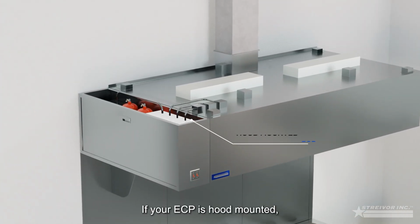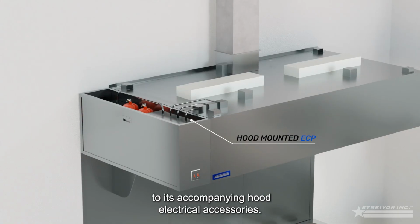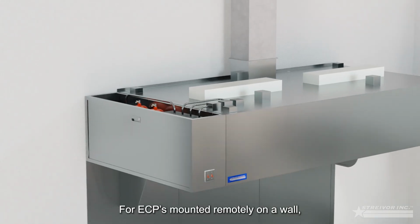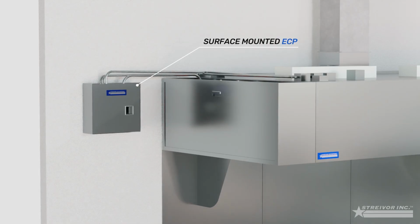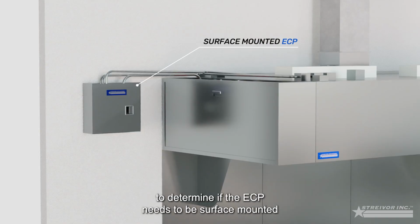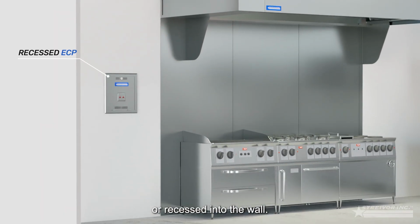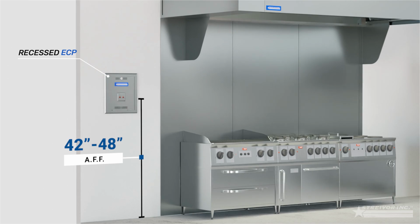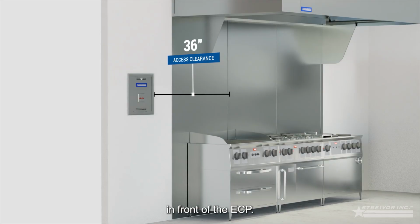If your ECP is hood-mounted, it will be pre-wired at the factory to its accompanying hood electrical accessories. For ECPs mounted remotely on a wall, the electrical wiring should be connected to its accompanying hood. Follow the ECP detail from the DemandAire drawing to determine if the ECP needs to be surface-mounted or recessed into the wall, along with the proposed height that it should be installed at. Keep in mind that 36 inches of access clearance is always needed in front of the ECP.